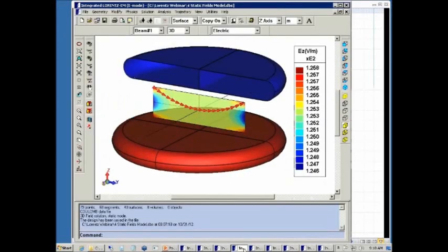We'll begin with a simple static analysis. What we have here are two disks, and I've made portions of them invisible. The top disk has a zero potential and the bottom disk has a positive potential, so that produces an E field in the Z direction. I'm launching a positive particle with a certain velocity against the E field and also a certain velocity perpendicular to the field. So what happens is that you describe a nice parabolic arc.